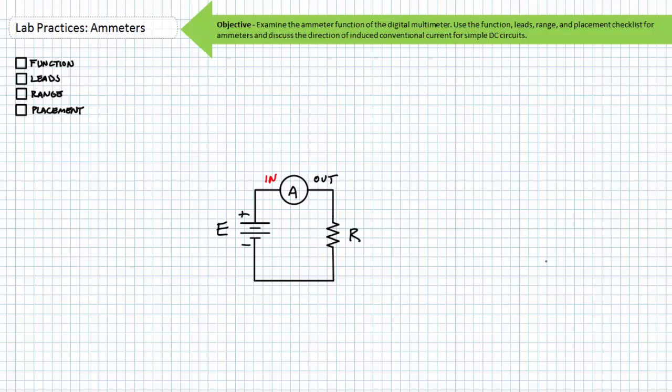We'll circumvent this modification necessity when I introduce a special purpose meter called a clamping ammeter or a clamp meter in later lectures. For now, let's stick to traditional ammeters inserted in line with our device of interest. Take your time and think about placement before rushing into current measurements. I've found that students do better if they draw a picture and explain it to their benevolent, all-powerful lab instructor what they intend to do prior to making their first current measurements.